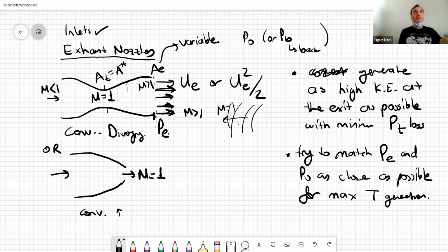There's another requirement that we need area change. So in some engines, in nozzles actually, we use afterburners. Okay. When we use afterburners, that of course changes the enthalpy level of the fluid, therefore increases in reality the total enthalpy, or H0, stagnation enthalpy level of the fluid. So therefore the nozzle can accelerate to higher and higher Mach numbers, especially if it's convergent divergent. Then in that case, we also need variable area.